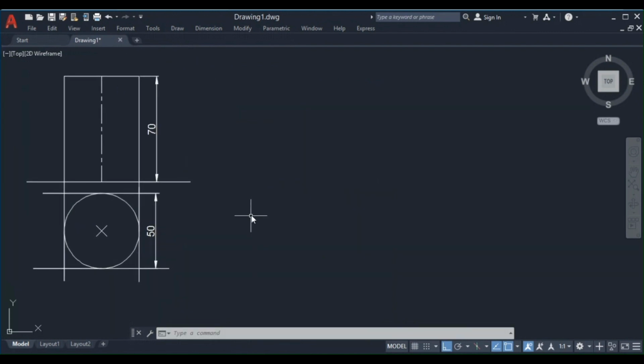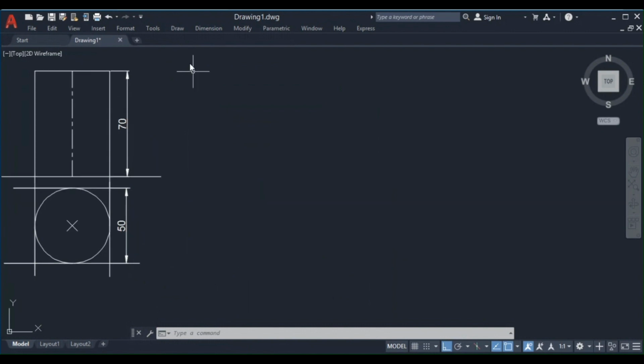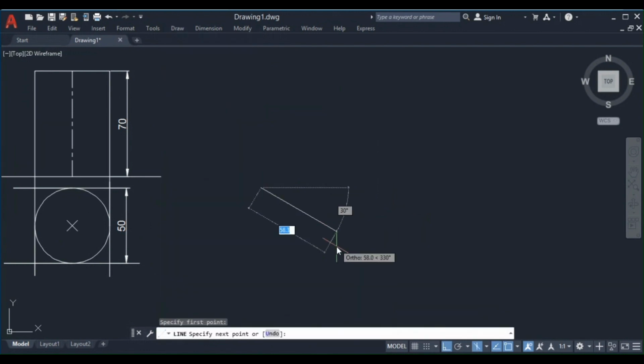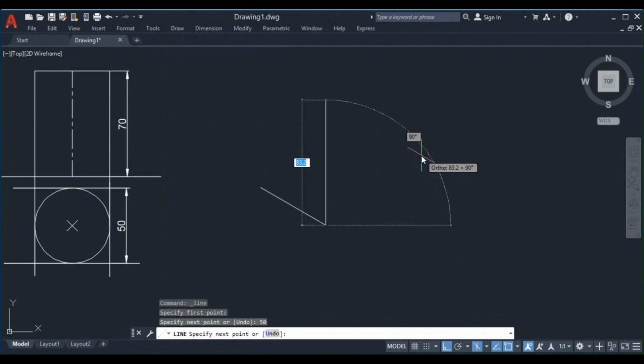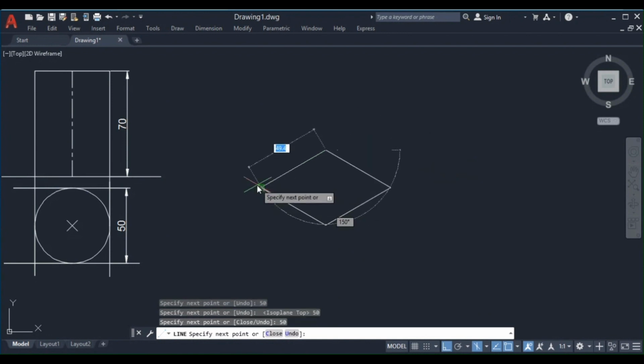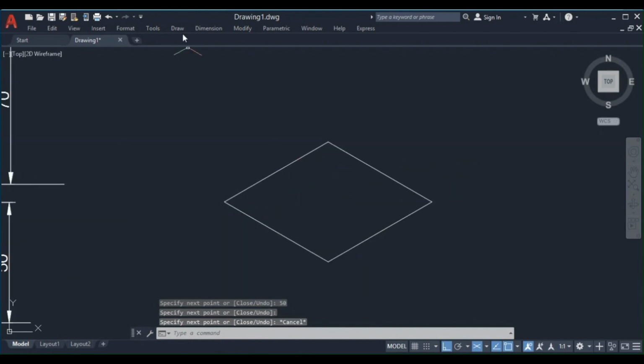So using 50, first I'm going to draw the axis vertical, that is axis perpendicular to HP. Right now, simple. So using 50 mm, construct the isometric view of a square, that is isorhombus, using 50, plus 50, plus 50. So first join the major diagonal.